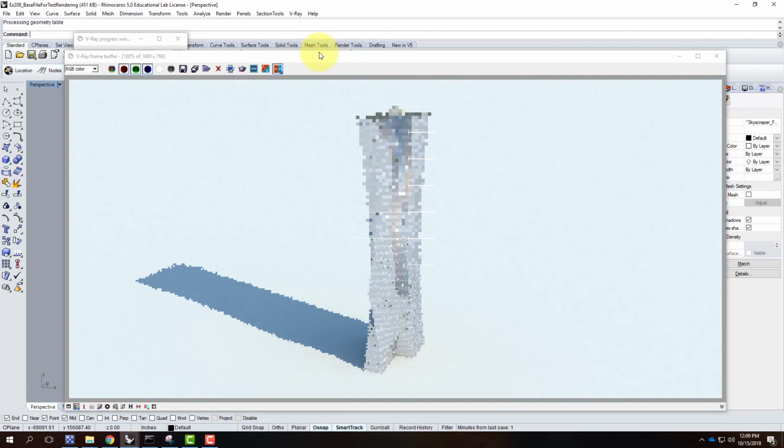So that kind of makes sense for the trajectory for today. So the first hour or so, just play around with form. Have a good time. I mean, I did 10 different buildings. Do 15. Just create a bunch and decide which one feels right. Once you kind of distill it down, that's when it's time to punch the core through the building. And then once you get that figured out, then spend the time with the materials and getting that identified, get your texture mapping correct, and then you can bring it over and do the actual rendering of it.